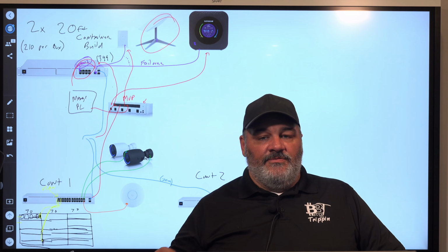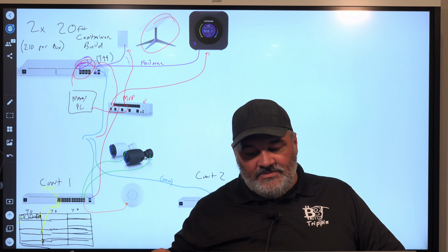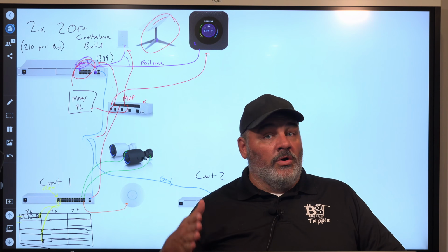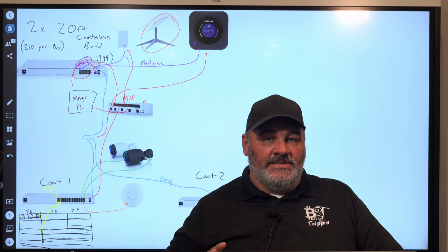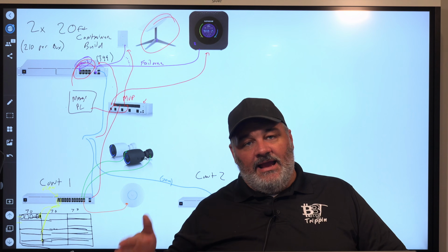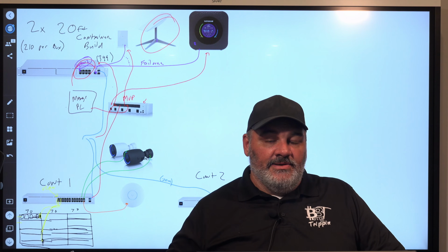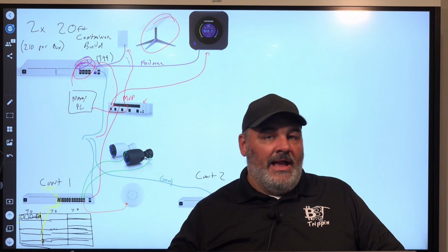If you don't have absolute control of what that machine previously was, maybe have it taped on there or something, and you have a worker or somebody coming in, maybe on a larger project you bring in out of town help, everybody's got to have that same understanding that if you go in there and reset that device, for whatever reason, it gets that new static IP. Otherwise, you're back into that cycle.